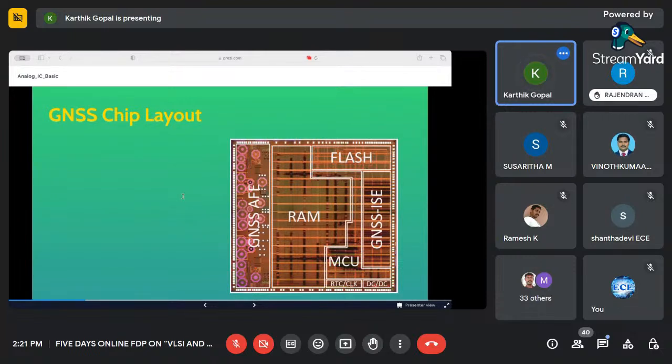So the major challenge here is coupling. Coupling means two lines flowing together. Let's assume we see an electric cable which is all over the place. If two lines come across, it may create some kind of spark. That is because of the coupling effect. When you bring them closer, it forms a capacitor, right? That capacitor comes into the circuit itself. So that is the complexity of this.